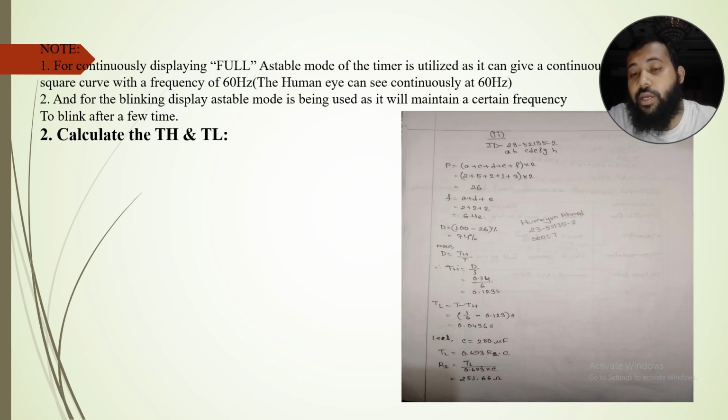I also calculated TH, which is 0.123 second, and TL, which is 0.0436 second. And here I also calculated R1 and R2.